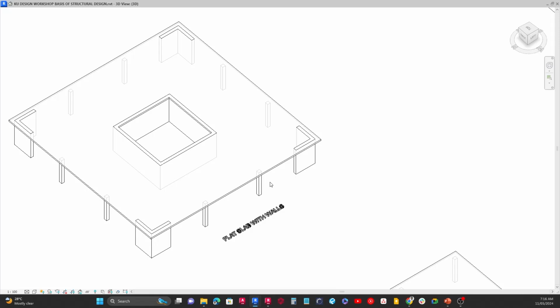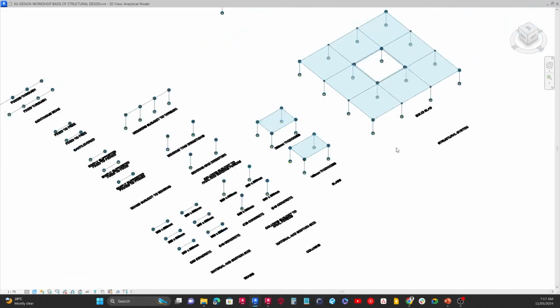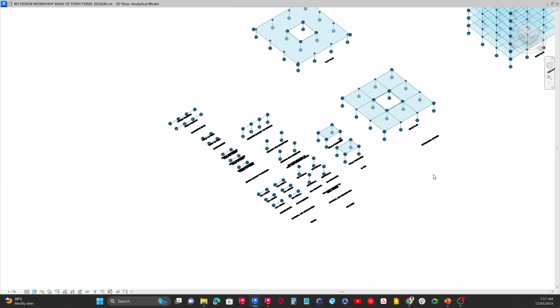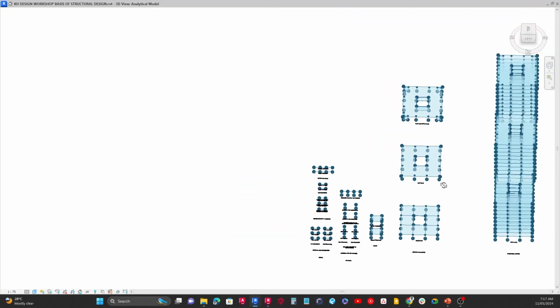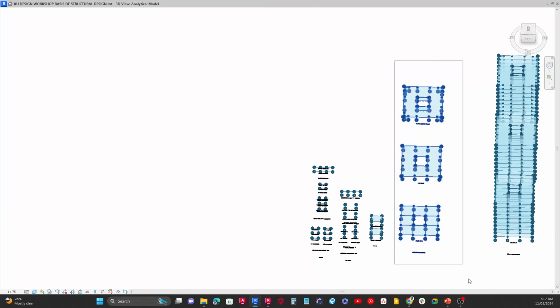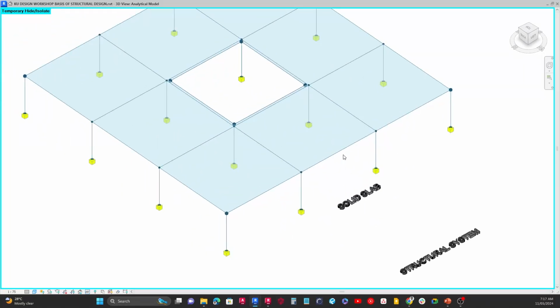We're going back to this analysis over and over again, so we can see that analysis is not something that should be defeated. So let's go ahead and look at the results, how they differ by system. What we want to see first is the results on the slab. Let's look at the displacements. I'm going to highlight all of this over here, isolate it, and look at the solid slab system over here. I'm going to check the results on the surfaces, which is the general displacements.